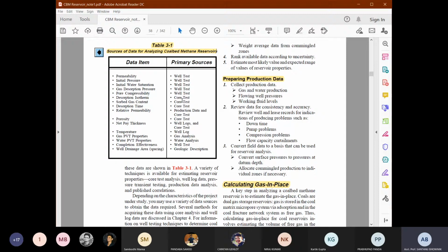That borehole zone of influence, if you are going to consider the 50-meter, within 50-meter, there is no fracture exceeding that 50-meter periphery from the center of the borehole. So beyond that, whatever rock strata will be lying, that will be in the far field stress zone. Do you remember this concept? I have discussed with you near field stress zone and the far field stress zone.